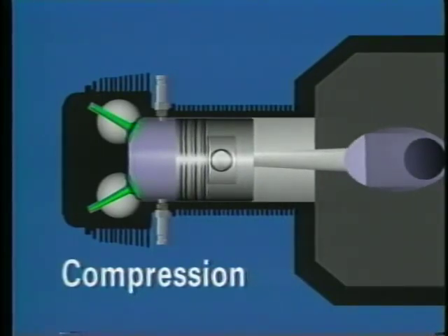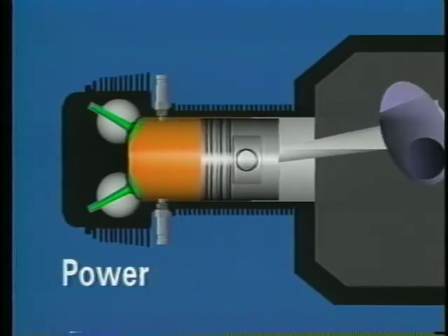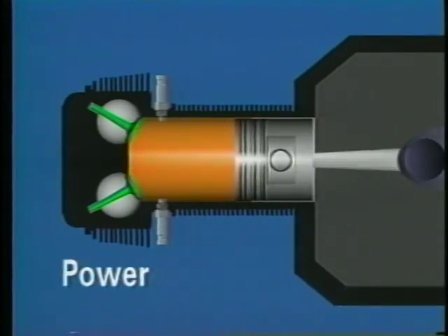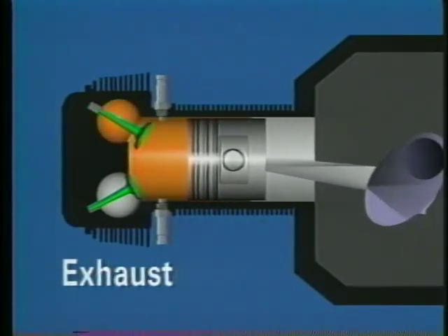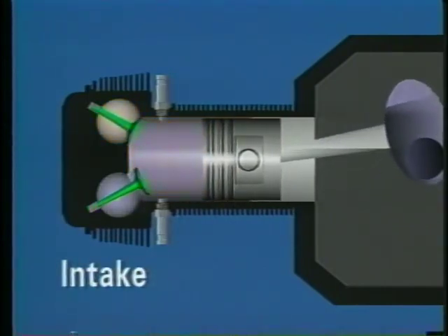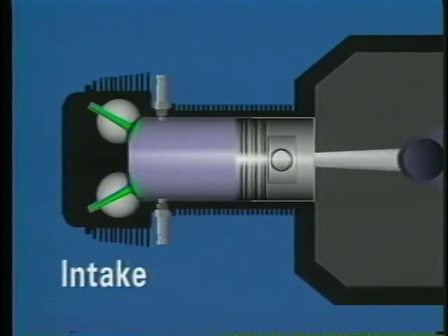When the compression stroke is almost complete, both spark plugs ignite the mixture. The combustion drives the piston away. This creates the power necessary to turn the crankshaft. Finally, the exhaust valve opens and the burned gases are forced out of the cylinder. In light training aircraft, this cycle repeats itself approximately 1,300 times a minute during cruise flight.